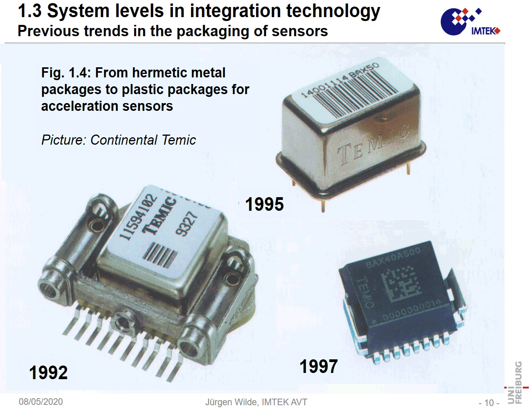It was a device that was in a metal housing. Also, the fixture at that time, we thought, must be very well defined in order to precisely monitor and record the crash pulse and then release or fire the airbag. The second reason why we had a metal housing was that a metal housing is what we call hermetic, so the chip is very well protected. And then the package was simplified.